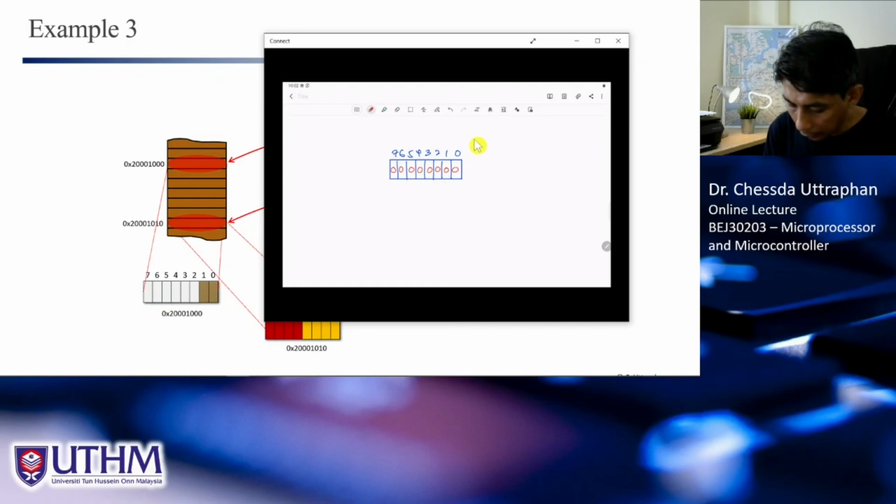And remember, the switch is only represented by these two bits, bit number 0 and bit number 1. So if inside here is this, it means that switch number 1 is pressed. So what we need to do is get this value into the microprocessor first.